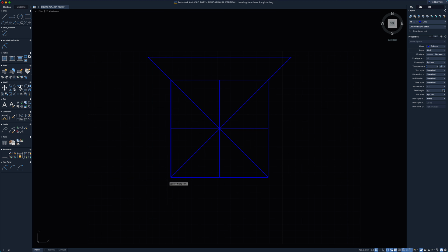And now repeat the process on the bottom, so 45 degrees, type in 50, right click out, right click in, and 45 degrees, snap to that point, 50, enter, and connect. And finally it says to finish this off by connecting that line and connecting this line right there.